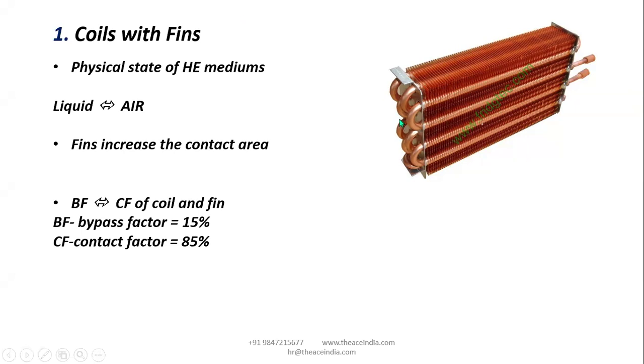When this coil is bent, it gets more time. If you use a straight pipe, what will happen? The refrigerant readily goes to the other side, but that's not what I want. I need the refrigerant to stay longer inside the coil, which initiates more heat exchange, isn't it? Because we need to bring the temperature of the refrigerant back to the saturation levels, isn't it?